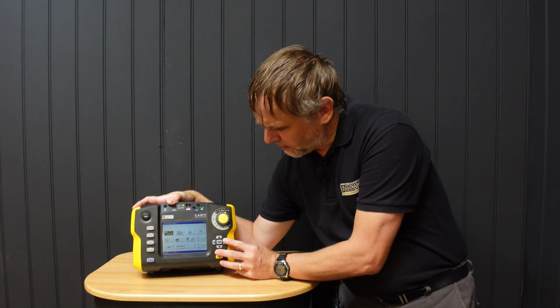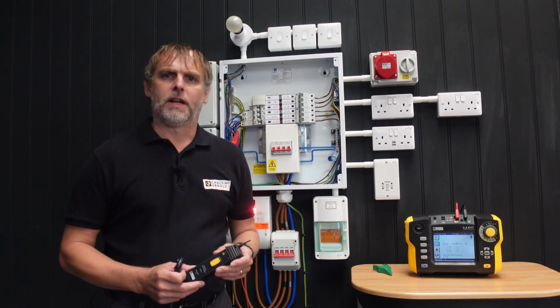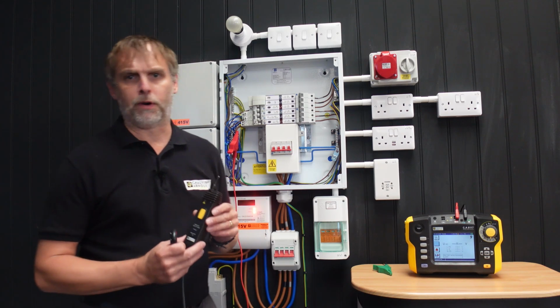One thing to note with the audio feature is that for it to work, the audio must be set as on in the global setup menu, as that overrides the individual test settings. If the global option is set to mute, then the instrument will not make any sound on most tests, although the display will still visually show either a tick or a red bell icon for any result below or above the programmed threshold. Insulation resistance may be performed using either the red and black lead set or the remote probe.